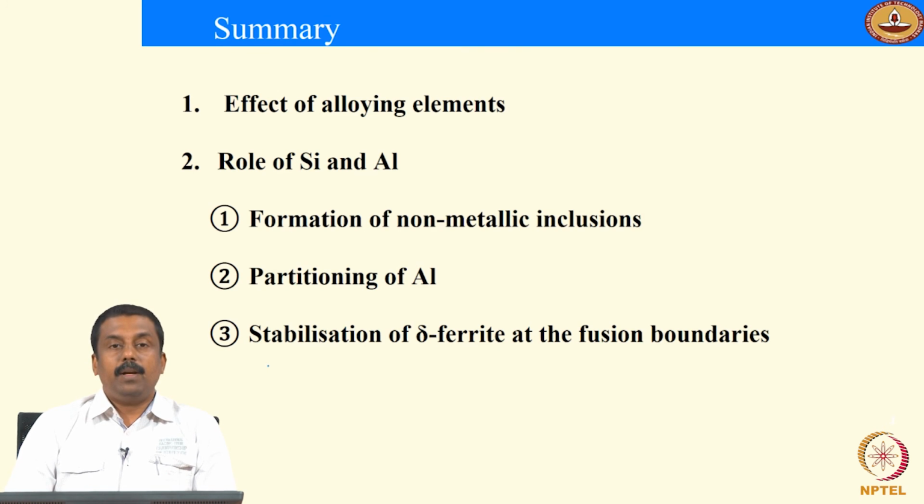And if you form very bulky, large non-metallic inclusions, you would expect the weld metal properties to deteriorate significantly. Therefore, it is very important to control the environment, especially the presence of oxygen during welding. If you use GMAW, the use of a proper shielding gas, as well as atmosphere protection of the liquid melt, is extremely critical in controlling the size and volume fraction of these inclusions.